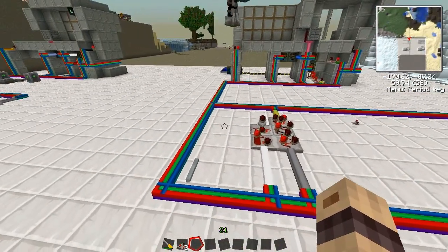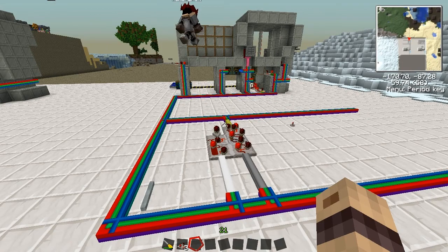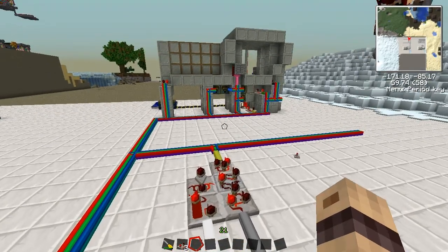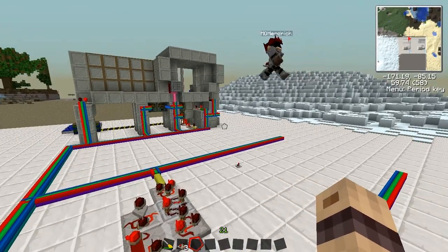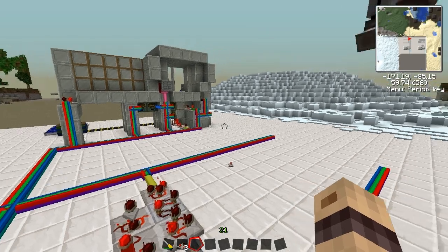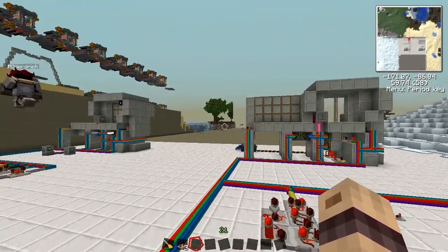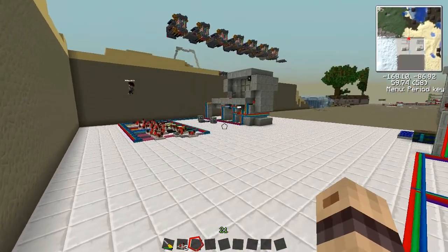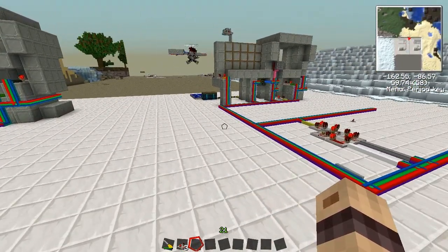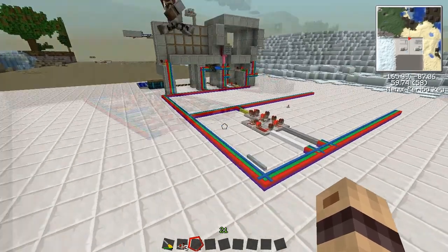And the whole RS latch thing is to prevent the malfunctions caused by lag. You could also imagine setting up timers and waiting for a certain amount of time and then switching off the signal. But especially in multiplayer platforms, this is very unstable. So it's better to use those sensors and actually keep track of the state of the system with those latches.